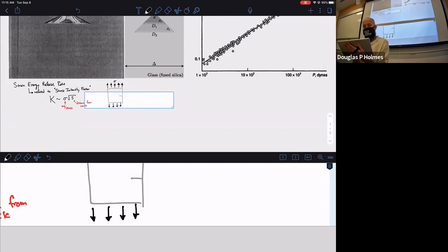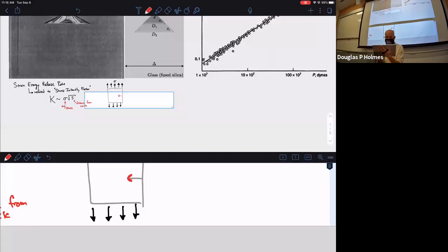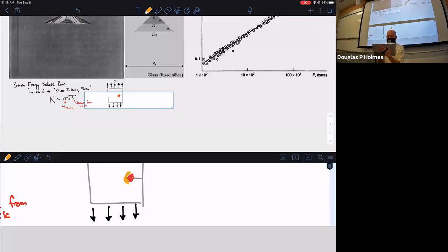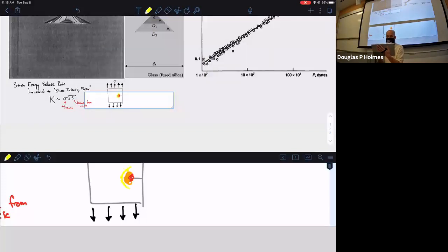And what this stress intensity factor is saying is that the stress in this sample is going to be the average stress amplified by how far you are away. So the closer you get to, say, here, the higher the stress is going to be. So larger stress, you can go rainbow, less large stress, and so on and so forth. Which matches our intuition. The stress should be larger near the crack tip.